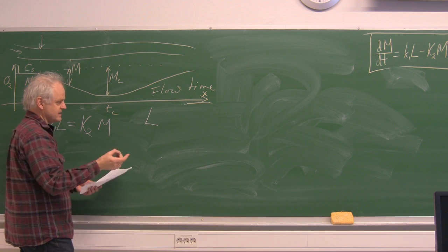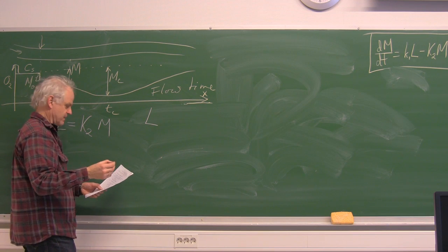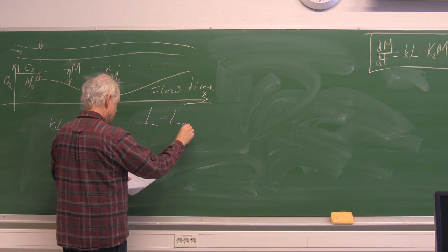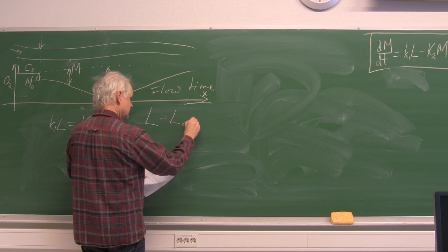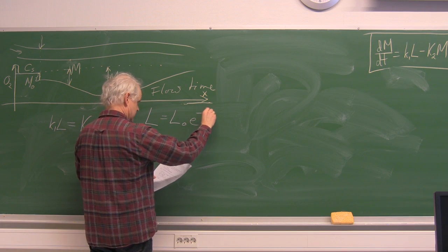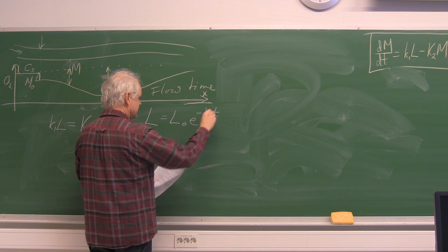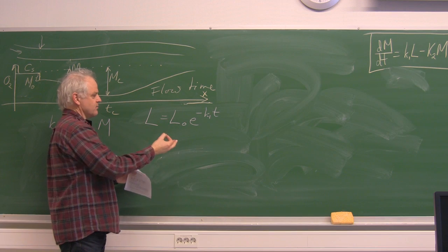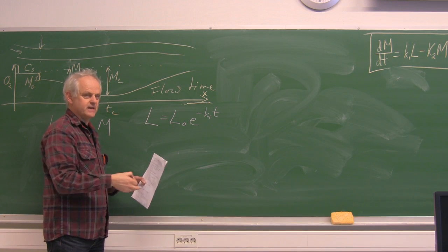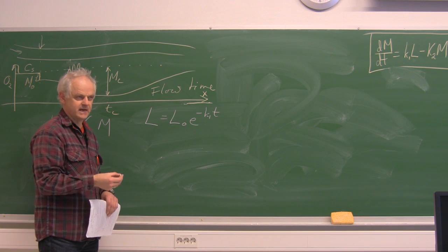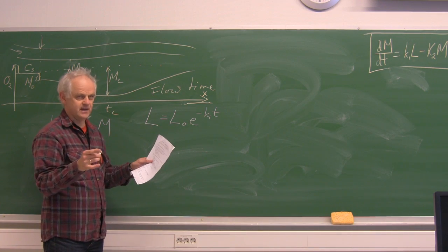That is typically expressed, and you can read about this in the book about BOD, as L = L0 e^(-K1 t). That's how BOD is disappearing gradually. It's the equation you come up with if you just look at what's happening in your BOD test over time.